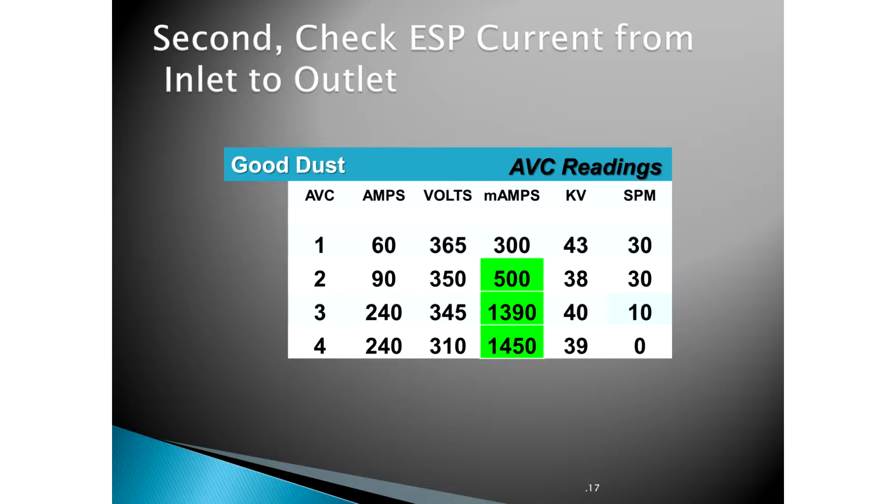And he's right. Don't complicate your lives. If you had to examine and review a precipitator, as long as the current increases from field to field to field, it's doing its job. You've got too much else to worry about. If you have a problem, give me a call, please.